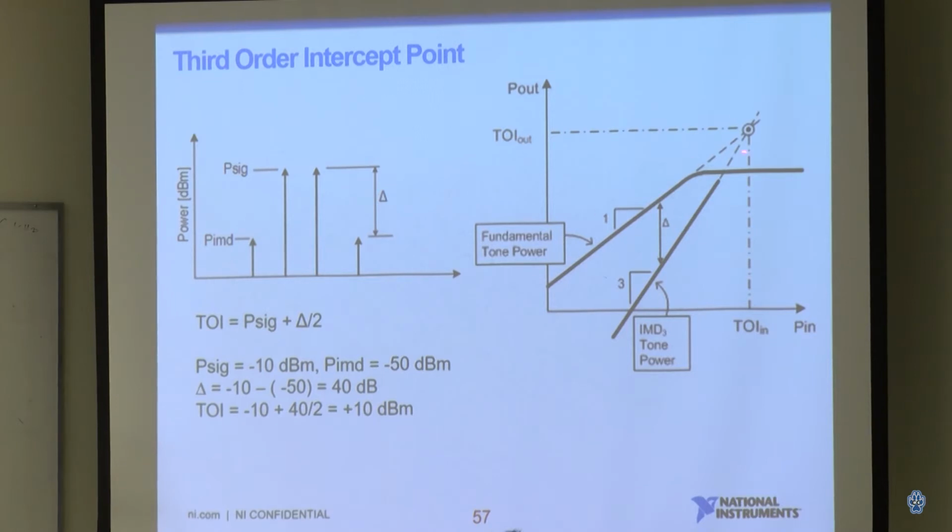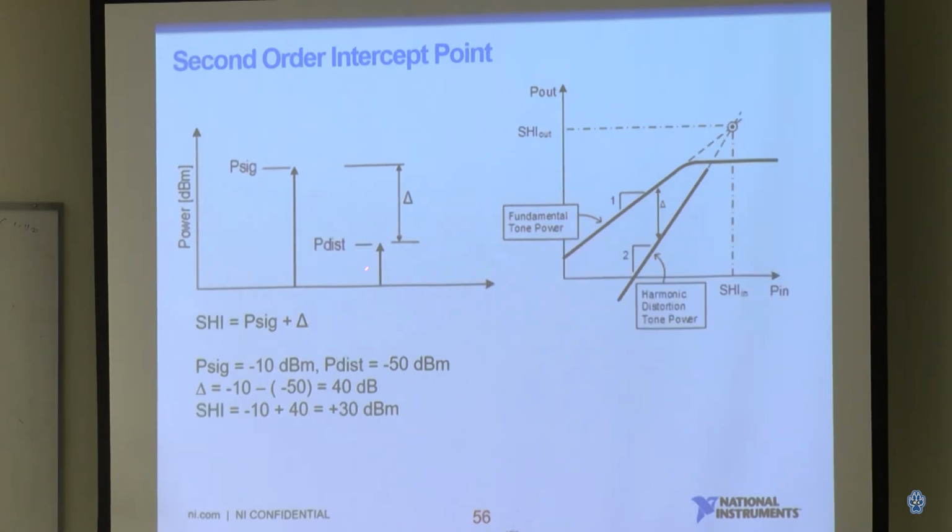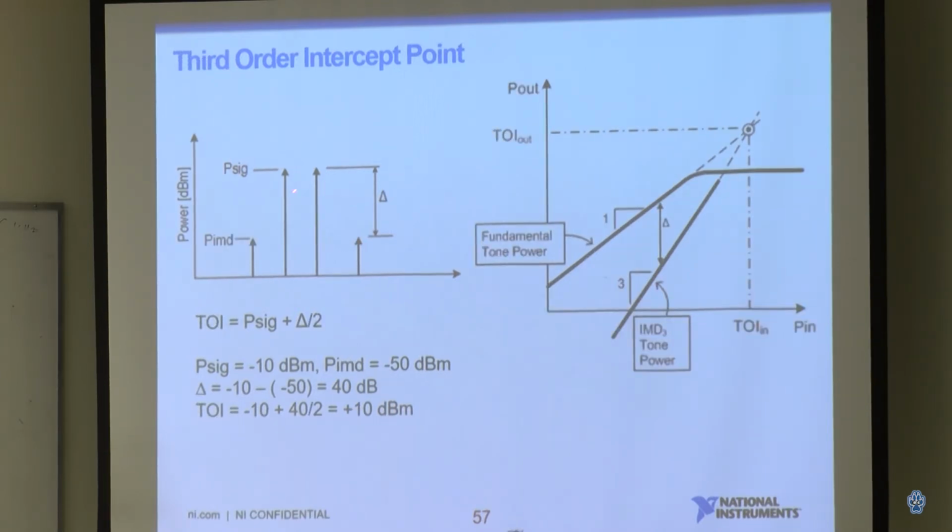And this is the third harmonic chart. Same idea as before when we talked about the second harmonic. When we talk about the third order harmonic, you want to use two input signals to calculate their third harmonic products. And same idea, right? You calculate the TOI point versus different input power. Is this point higher and higher? That means your system linear range is bigger and bigger.